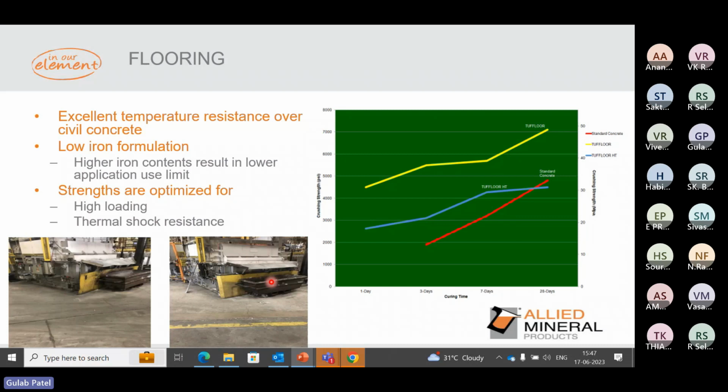Those floorings also have very high strength, so mechanically they are going to be less damaged, as well as from the metal. Both ways these floorings are going to be less affected, as well as when sometimes dross falls directly over the flooring. Because of the thermal shock, concrete or brick is going to be damaged very fast, while these special floorings are going to stay for a longer duration.